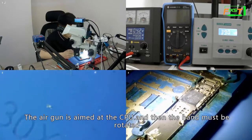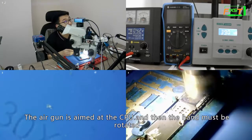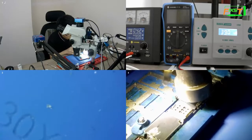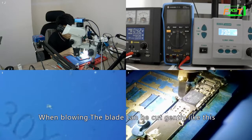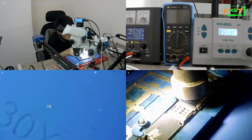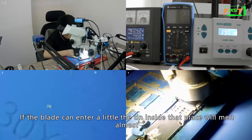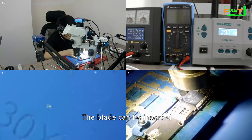The air gun just aims at the CPU, and the hand must keep rotating to let the CPU heat evenly. When blowing, the blade can be cut in gently like this, so that you will know whether the tin has melted or not. If the blade can enter a little, the tin in that place has almost melted. The blade can be inserted.